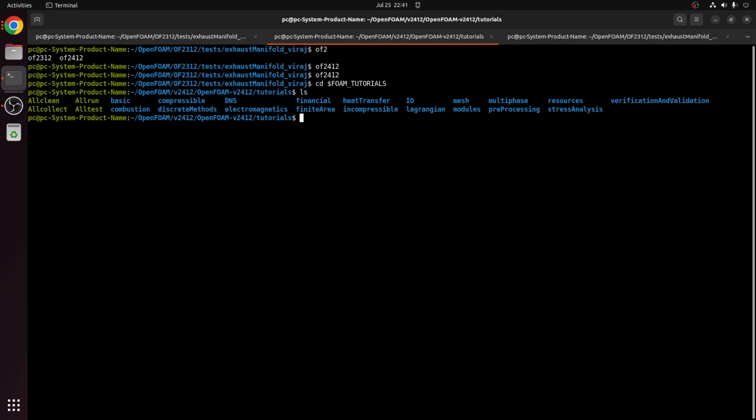go to something called foam tutorials. Basically, how we are going to create a case is we will take an existing case setup, copy it to our folder, and replace the files and settings on the boundary conditions based on our geometry. For the first simulation we are going to do a simple incompressible turbulent flow case, a pipe flow case kind of thing.